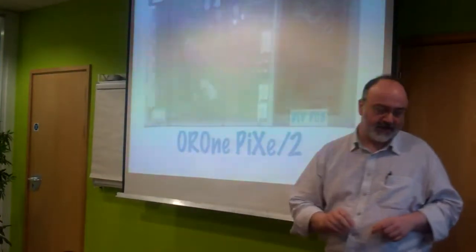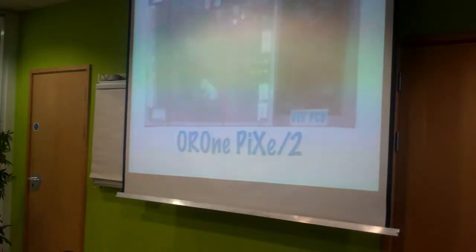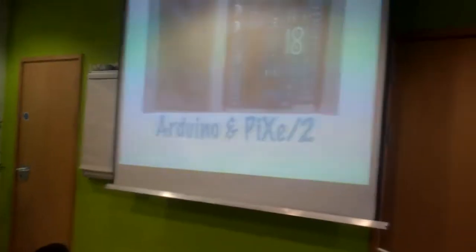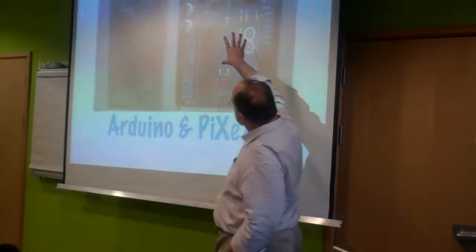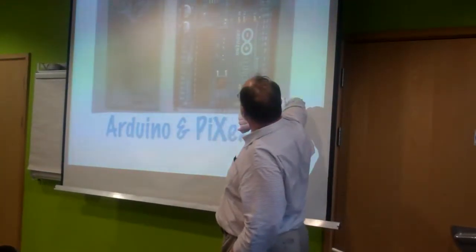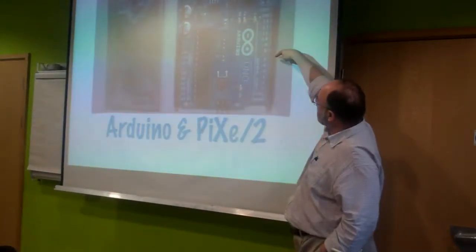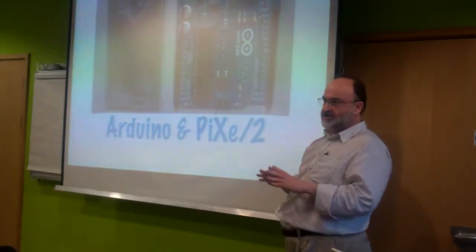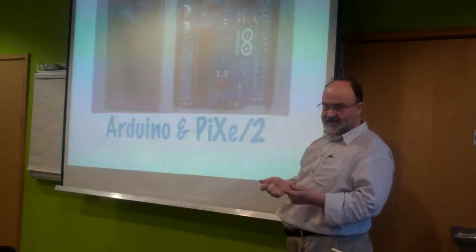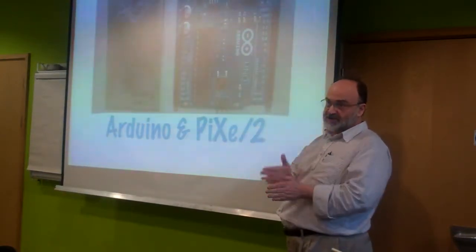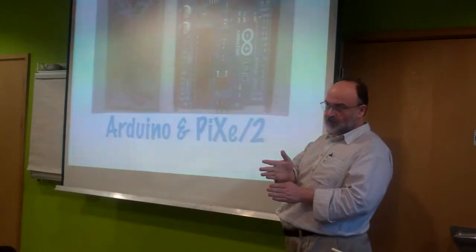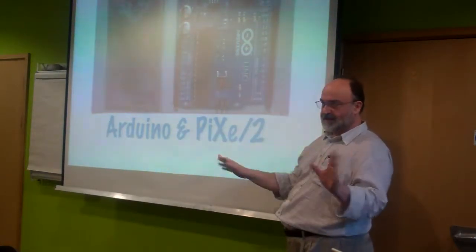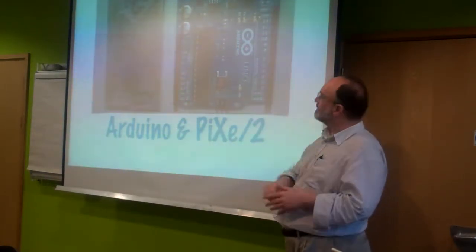And so just to give you a physical comparison, that's the size of an Arduino, and one of the problems with this guy is it's not on a 0.1 pitch. 0.1 inch pitch is wonderful. There's lots of electronic mechanisms around which, if you can get onto a nice regular tenth of an inch pitch, electronics plugs together beautifully.